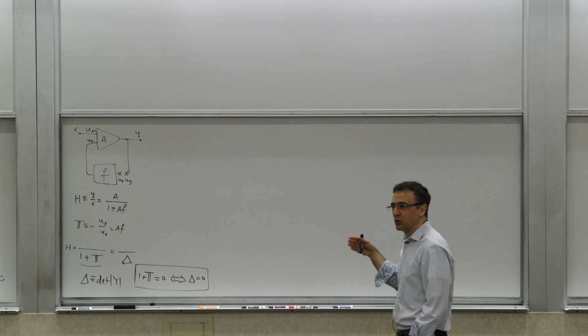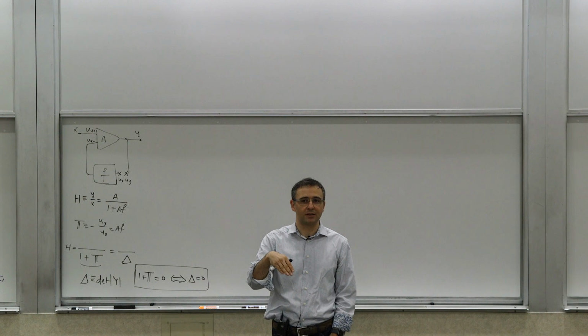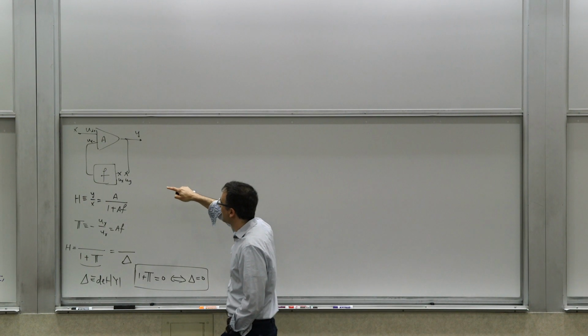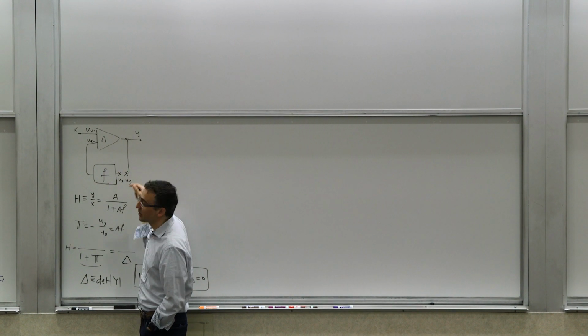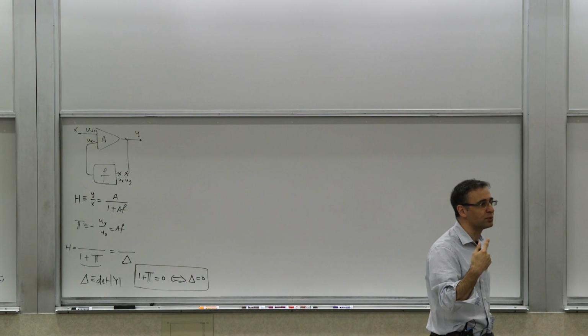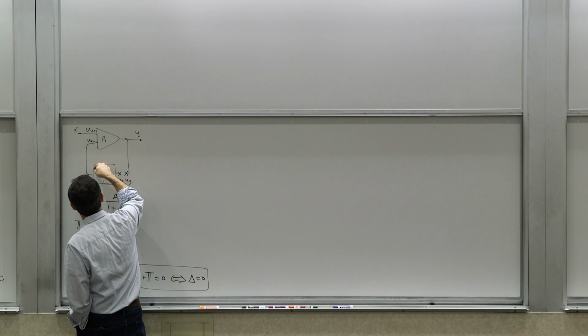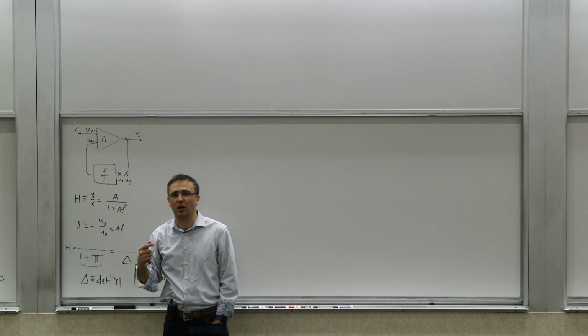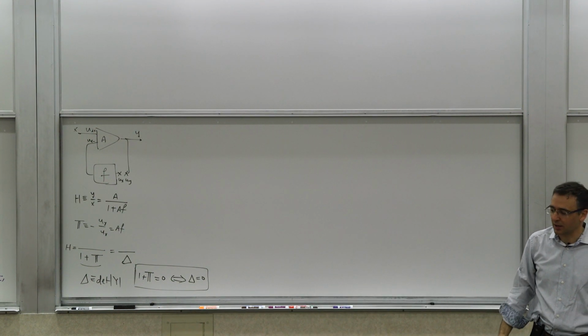And we saw that for the unilateral loop, we have already determined what it is. It was basically 1 over the sum of the reciprocals of the voltage loop gain and the current loop gain, the forward loop gain. But now what if you have a bilateral loop? Basically, a loop where the signal can also travel in this direction, in addition to this direction. So it can go both clockwise and counterclockwise. What would we do and how do we modify it?